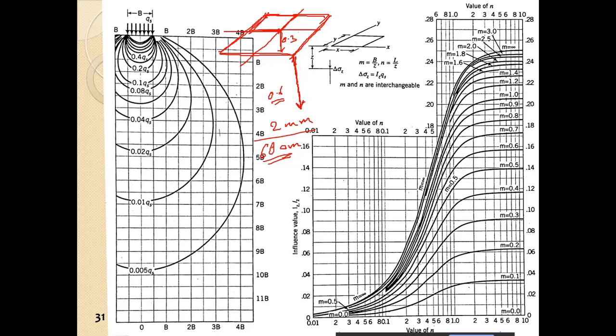So if we consider only 1/4 of the plate, this is 0.3, this is 0.3 and this is 0.3. So it becomes easy to find out the delta sigma Z, or increment in the stress, at that point. I hope you remember this. This is for analysis of elastic settlement when you study the foundation system. Obviously this is not in our course, but just to know how to find the coefficient of uniform elastic compression from the cyclic plate load test.